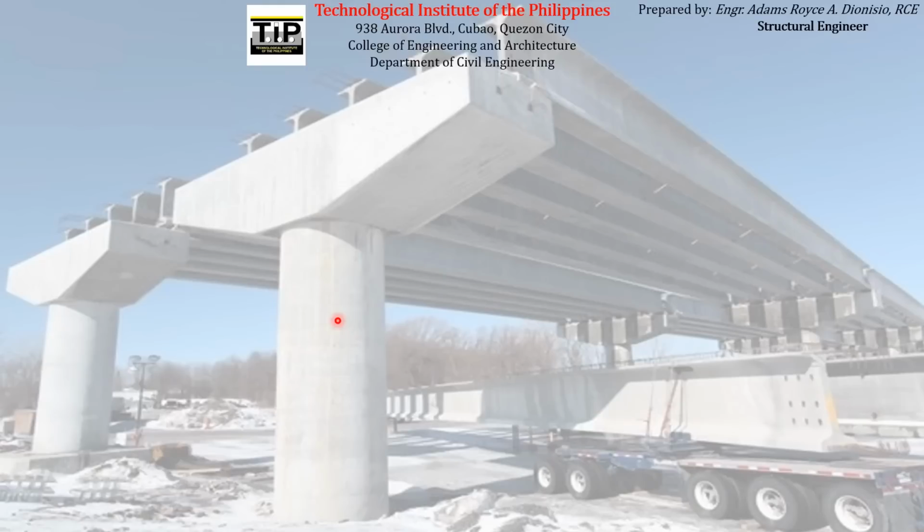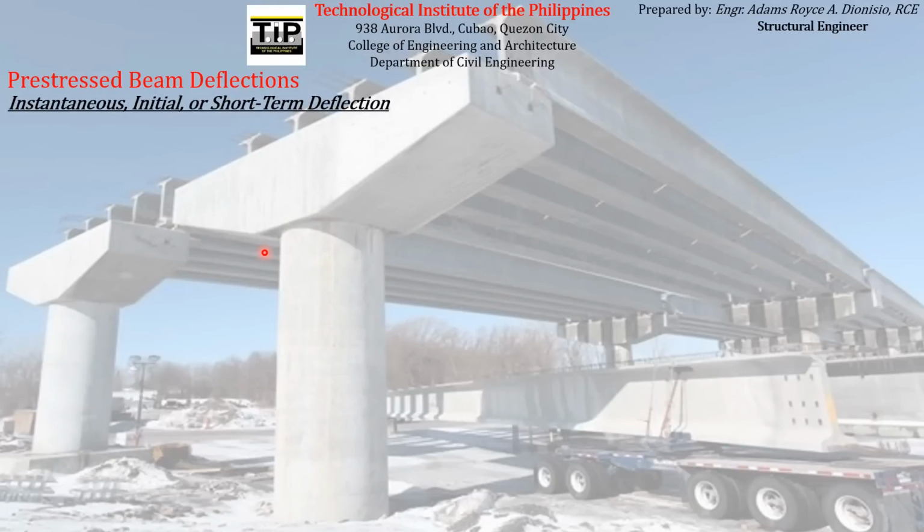So let us start the discussion on the deflections of prestressed concrete beams. Actually, there are two types of deflection that are being experienced by a prestressed concrete beam. The first type is the instantaneous or initial or short-term deflection. These are the deflections experienced by the prestressed concrete beam as it supports the loads that are supposed to be carried by it in the short term.